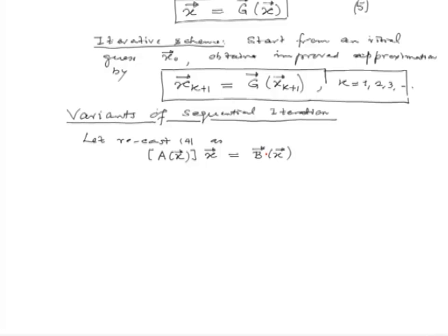Now, obtaining this form in fact is a lot easier when we are working with a discretization scheme, because that is the way we had obtained our generic equation. But remember, our equation was obtained in terms of these coefficients AP, AW, AE and so on for finite difference discretization. So, this is a more natural form of nonlinear equations which we would get while discretizing our PDE or partial differential equation using finite difference, finite volume or finite element method. So, this could be our starting point.